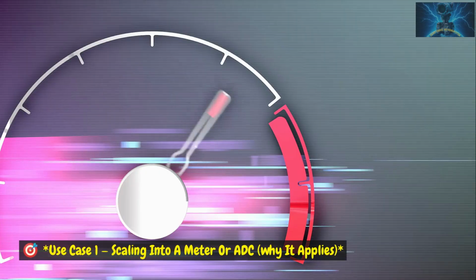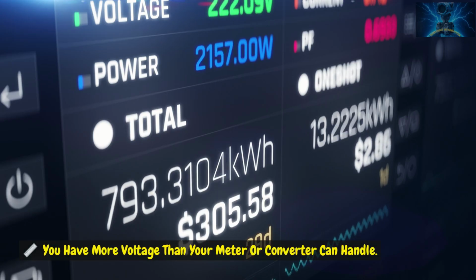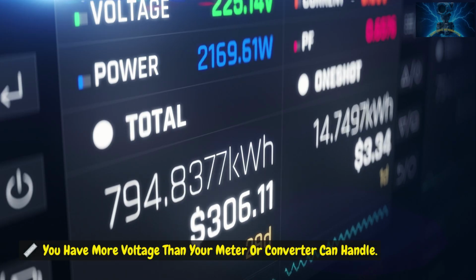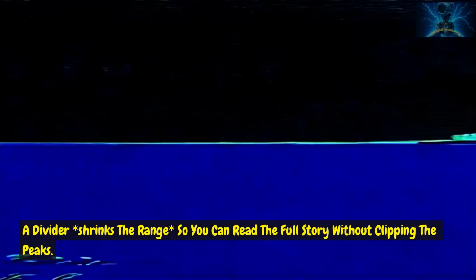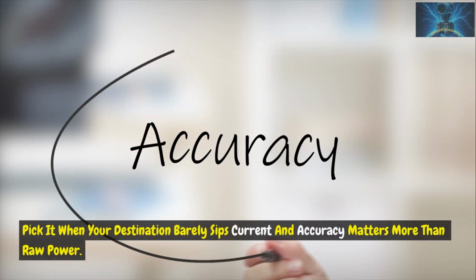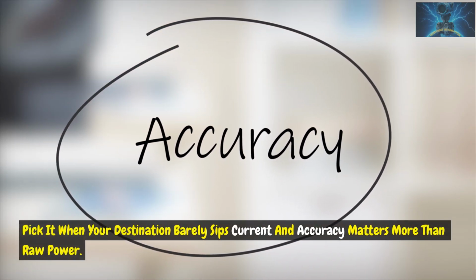Use case 1: scaling into a meter or ADC. Why it applies: you have more voltage than your meter or converter can handle. A divider shrinks the range, so you can read the full story without clipping the peaks. Pick it when your destination barely sips current, and accuracy matters more than raw power.